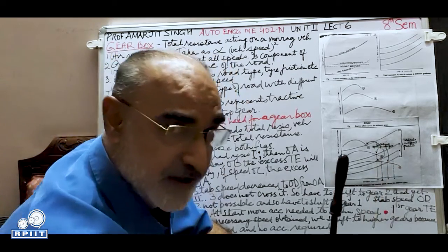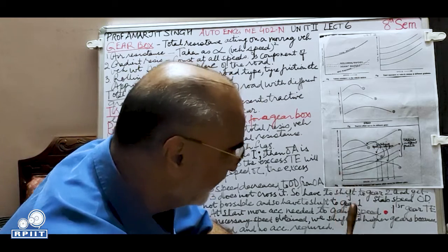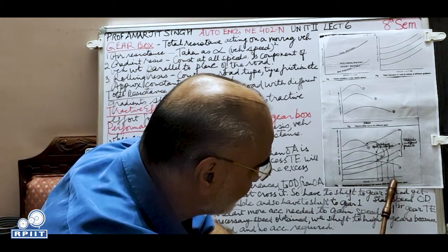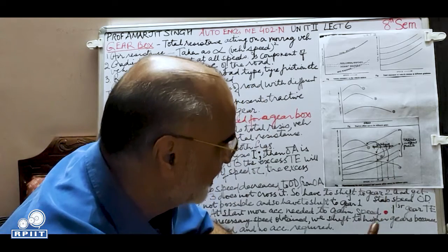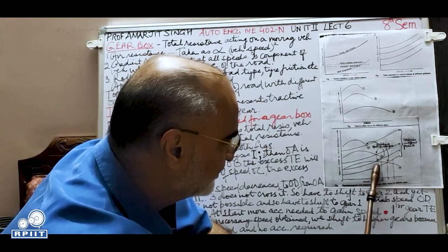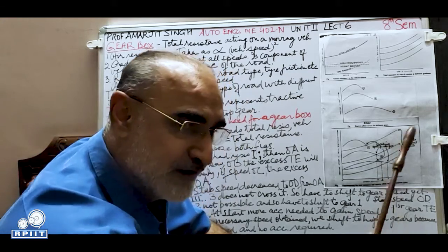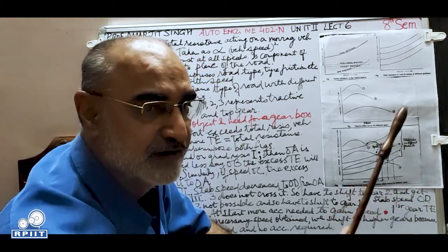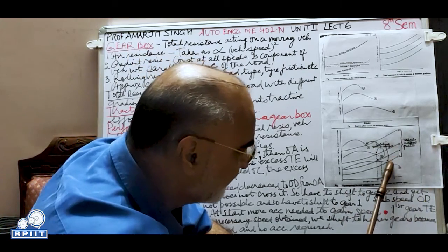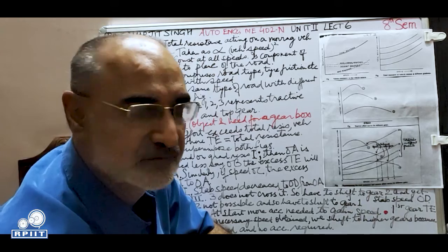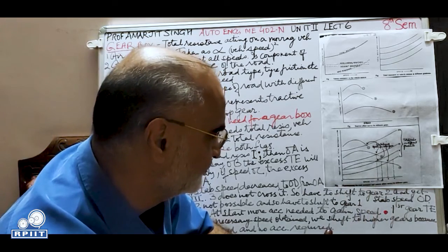Similarly, we are still in the third gear, remember. Similarly, if the speed of the vehicle is OC, here the resistance is more, tractive effort is less. So automatically the vehicle will decelerate. It will slow down till it reaches the speed OA. I hope this is clear.